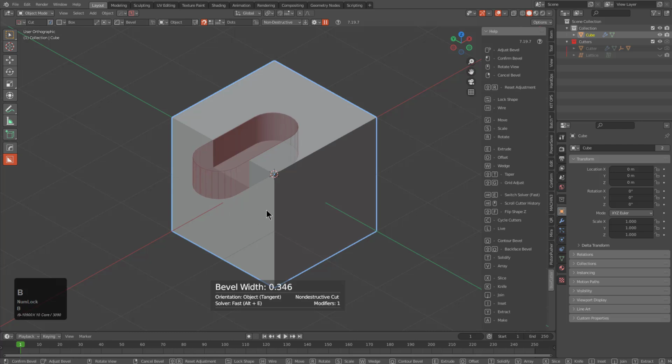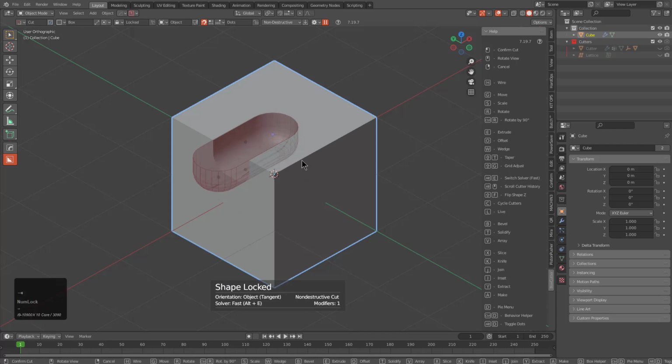So if I press B, I can bevel, where by moving the width in and out, I'm able to adjust the segment count to go from 1 segment to 6 segments, just allowing me to quickly get something a little more rounded if needed. Another thing about the bevel is we see that there's a hotkey of Q, where basically if we press Q, we bring in something called the Q bevel.